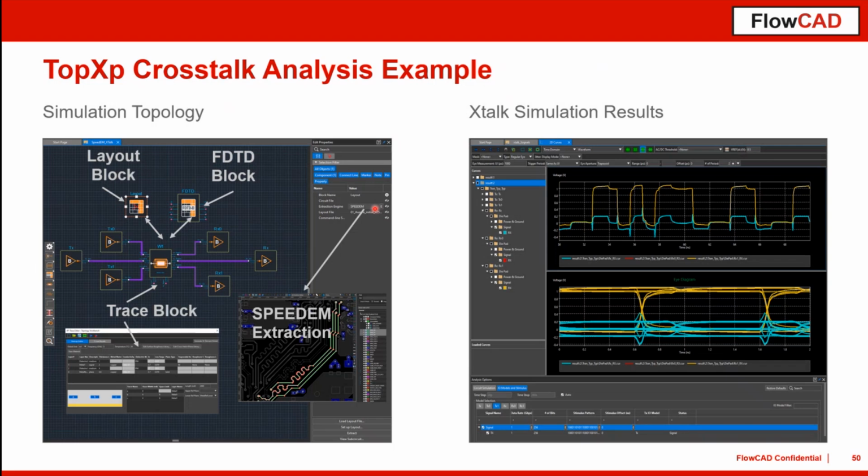If you need much more accurate models like S-parameter models, you may also choose Power SI for extracting S-parameter models, or high-end, high-frequency S-parameter models using the Clarity 3D EM solver. This can be checked out over this extraction engine. But since we have two tokens on hand, we are limited to the Speed EM extraction.